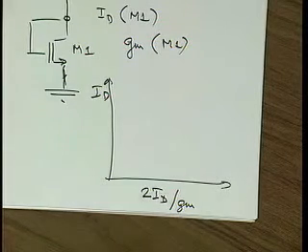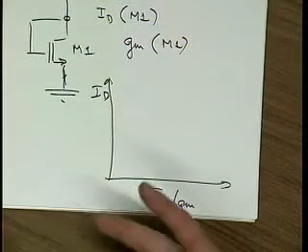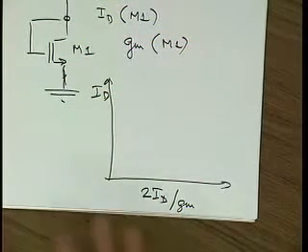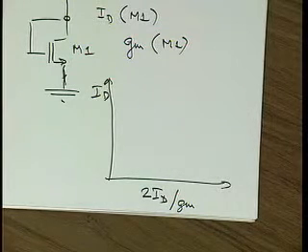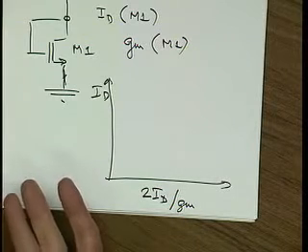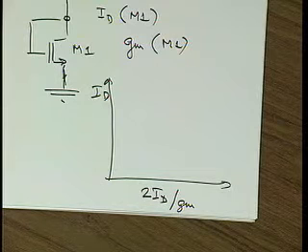So very often when we design for a real chip, we actually design for kind of the worst case from the start, right? Okay, the nominal supply voltage is 3.3 volt, but we have plus minus 10%, so we design for 3 volt from the start. It doesn't help us that sometimes we're actually going to get more voltage. Right?